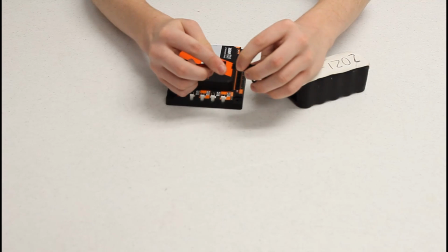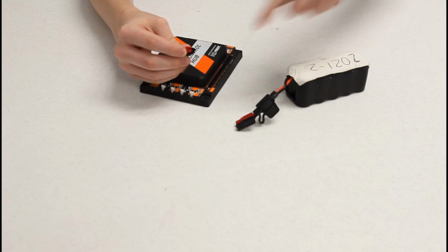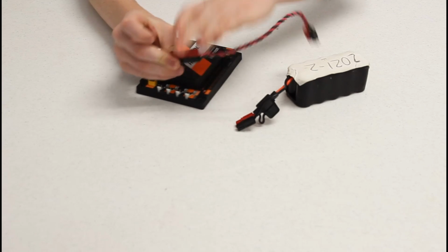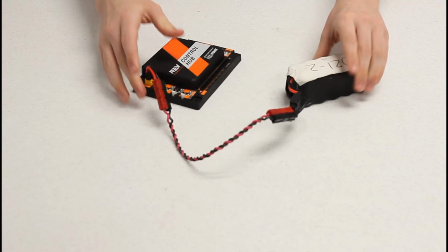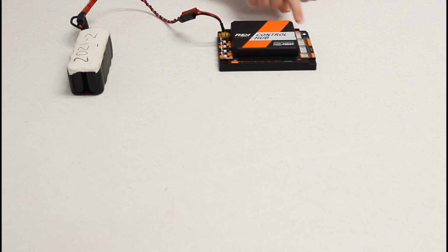But for the next step, if you try to plug in the battery to that, you can see that it ends up checkered. That happens sometimes with these power pole cables, so if that's the case, you'll need to grab an adapter cable like that. That flips the polarity. And now, it's not checkered, because you never want to leave those power pole cables checkered. And you can see this blue light turns on. Once that turns green, that means that the network is up and you're able to connect to it. But while we wait for that, let's grab our driver hub and get ready to connect.